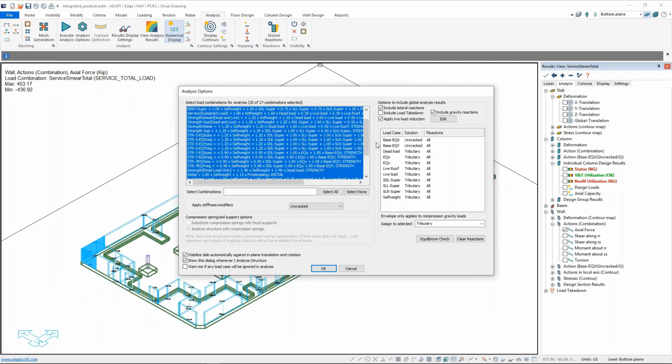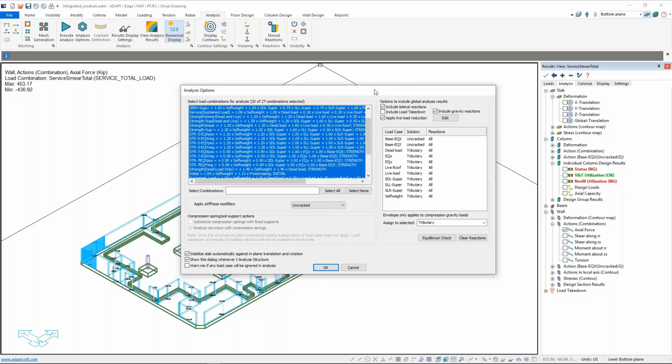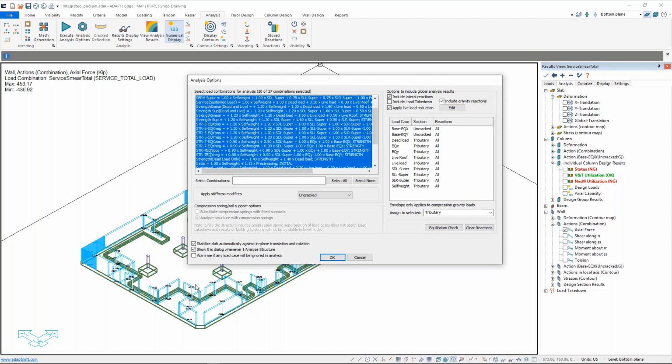So to answer not the magnitude, but at least the question of procedurally how, when you're applying your loads to the mat, to the lowest level, you would go ahead and apply them. You can then classify that load case as reducible, trigger the live load reduction, and then come in and use it.